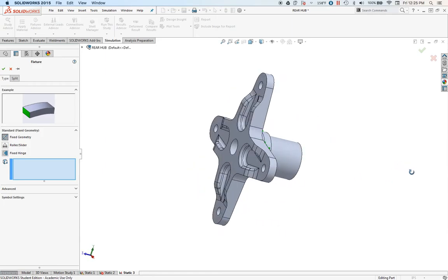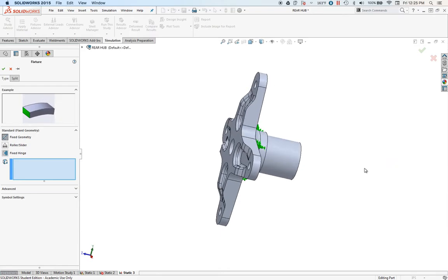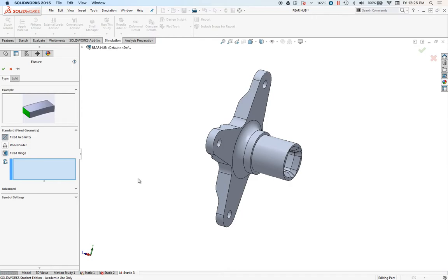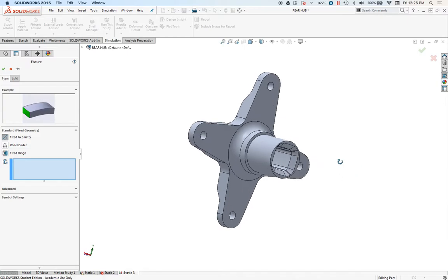So I'm going to come around to the back here. Basically, what I'm going to be doing right now is trying to simulate an impact on one of these tongues. You have the rim bolted on here, and let's say the Baja car starts sliding sideways, and we hit a rock, and it slams in. Worst case scenario, and all the force is directed onto this one tab. Now, that's not a super accurate simulation, I guess you could say, but it's a really good starting point to give you a ballpark estimate of if this part's even going to be close to working.